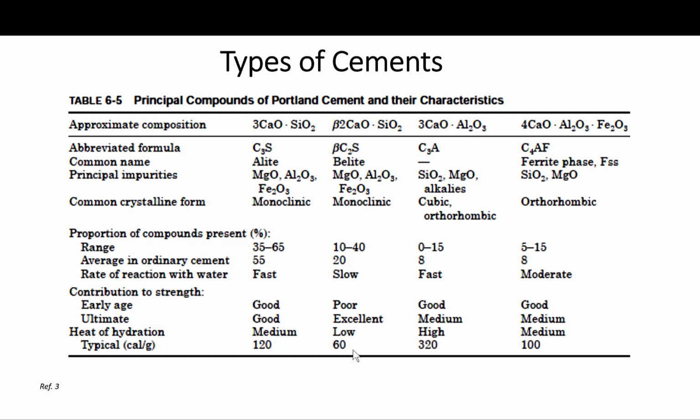So now you have an idea on how to select a cement for a certain application. Like if early strength is important, for example, we need high C3S content. And of course, fineness in order to increase the rate of hydration and strength gain. If sulfate attack is an issue, as I mentioned, the problem is with C3A. C3A and SO3 contents are important.